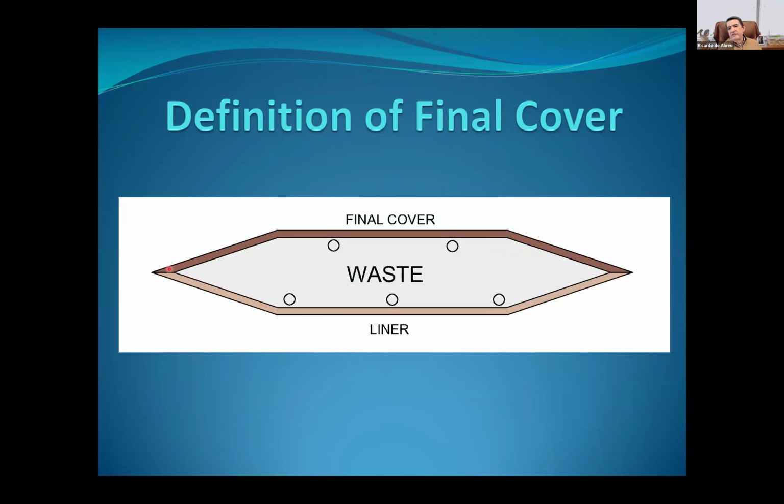When you build a landfill, and I know I'm going very to the basics here, you excavate your landfill, you put in a liner, you put in your leachate collection system, you put in the waste. You may have a gas system. Most of the landfills here in the United States now have a gas system. And in the end, when you are done with the site or with the cell, you install a final cover.